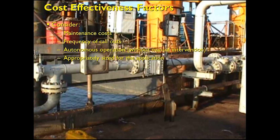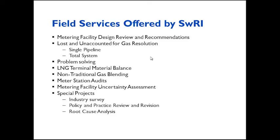Some factors that go into cost effectiveness are maintenance costs, frequency of call-outs. You know, it's nice if you save money putting in this single run orifice meter station, but if you have to go out and continuously be changing plates to meet the demand, then it's not such a good thing, and that doesn't accommodate autonomous operation. So that needs to be considered.